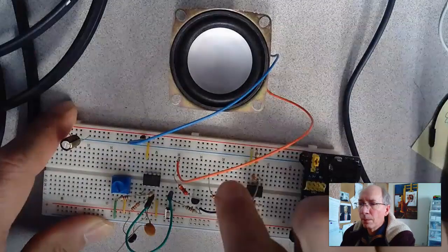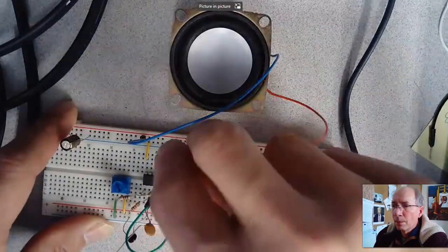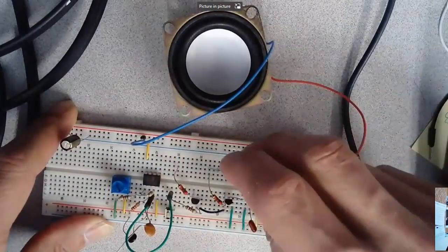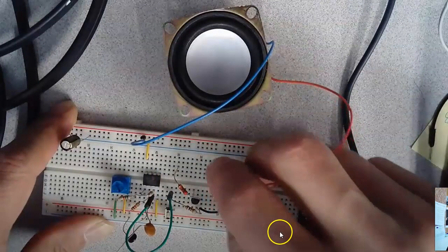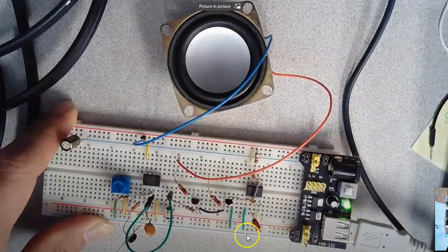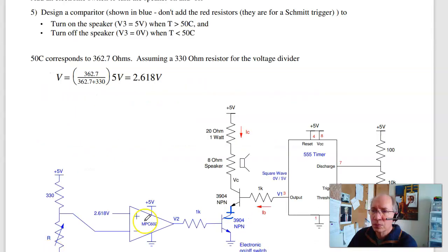And instead, if I use the transistor switch, that's my transistor switch. Here's the 20 ohm resistor, along with the current. I get a loud sound. Take the second transistor. Okay, so that verifies that my speaker is working.